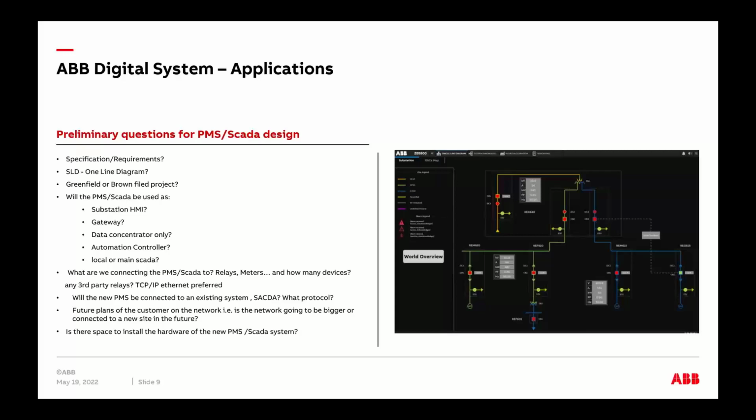Remember, devices are not equal. What I mean by that, one device can pull 20 signals maybe, the other one can pull 30, 40, 50, maybe 100 signals from it. So you need to do this equation depending on their plans for the future. If they tell you our substation is going to grow from 1 substation to 5 substations, total will be 300, 400 devices from day one, just give them either 7,000 tags or unlimited tags. You've got to have that conversation from day one when you're designing a system.